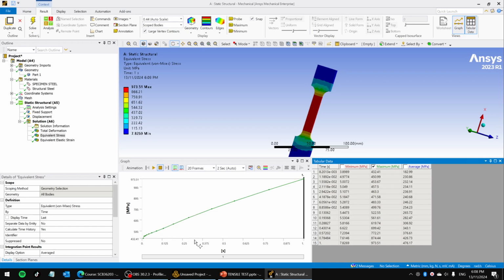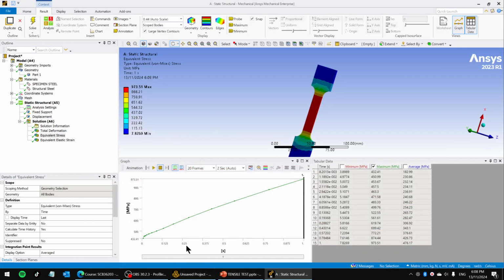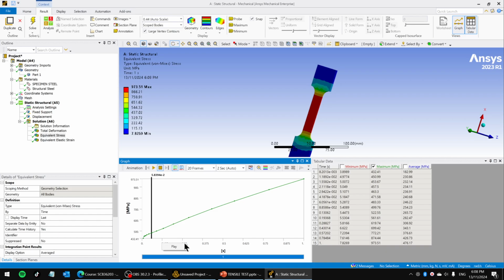So our material data, as what we key in at 0.0, it's going to be 500. Is it correct? 0.03 somewhere here. How do I make this value smaller? 500 is supposed to plot to 0.03. Currently it's plotted everywhere. So it's behaving as per our material database.